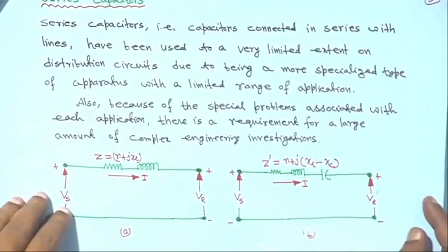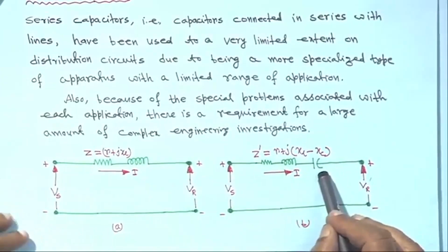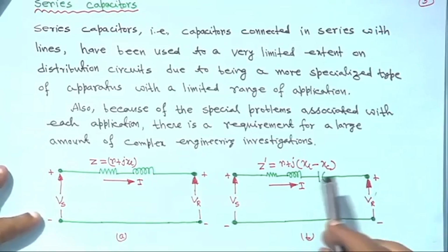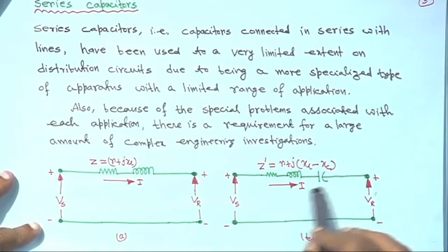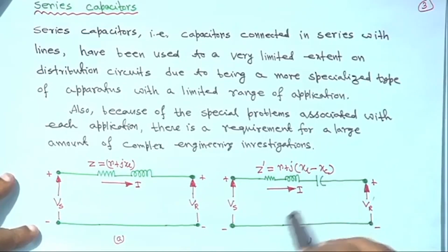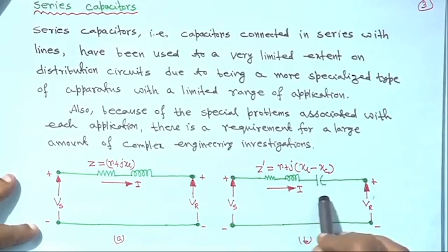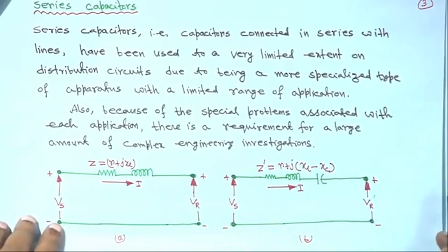So, it is analogous, they say, to something like a voltage regulator. Later we will talk about that a little bit, but Xc remains constant, and because of changing I, the reactive power generated by the series capacitor is changing. So, it acts like a voltage regulator. It is analogous to a voltage regulator, right.